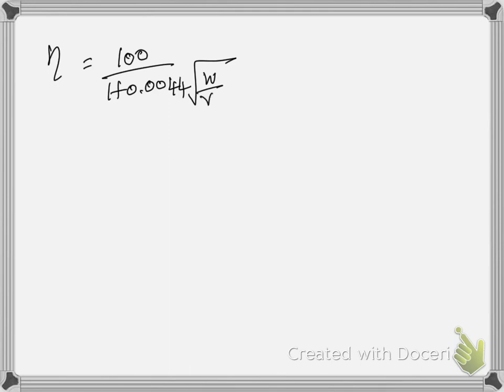Now I have to get the volume of the filter using the efficiency formula, that is efficiency is equal to 100 divided by 1 plus 0.0044 root of W by VF.